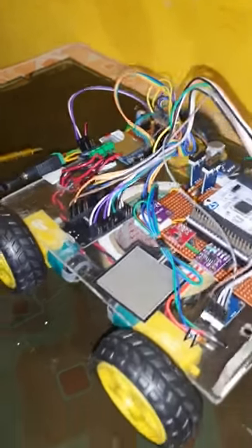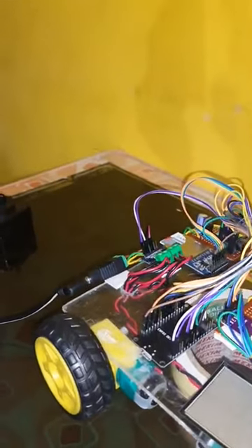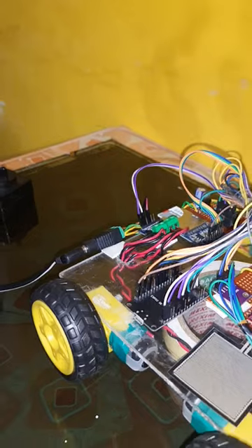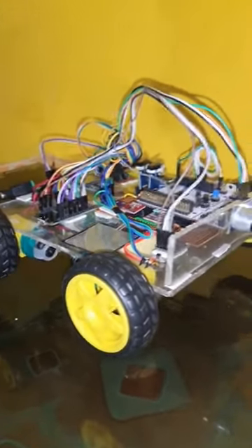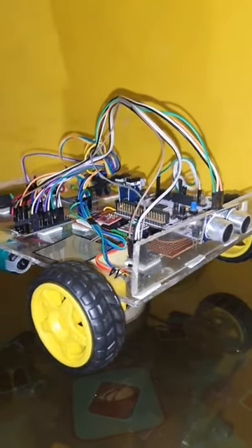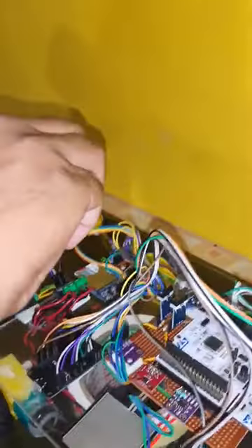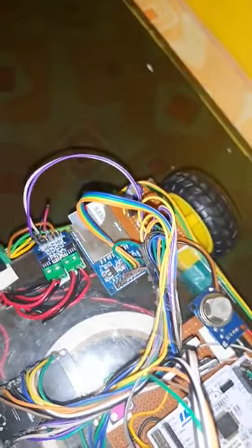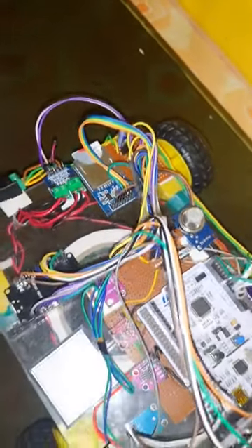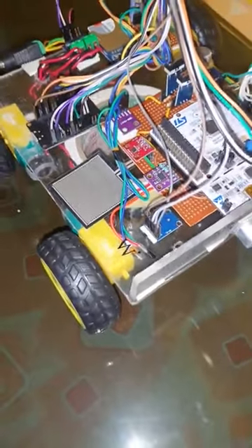We are using an external power supply for the STM, ESP and motor driver module, which is 12 volt output and 2 ampere. Basically, to convert the power from 12 volt to 5 volt we use a 7805 regulator. Here we can see we have used this regulator and capacitor to produce the 5 volt output. The 5 volt output is fed to the ESP32, STM and motor driver.